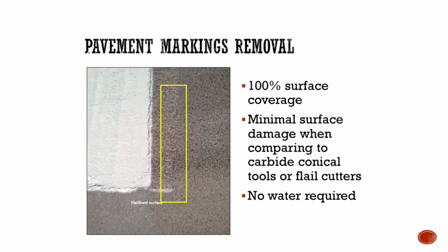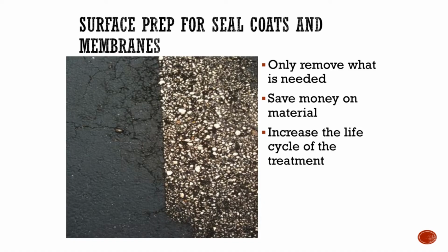Fantastic tool for pavement markings removal. In fact, we're seeing this all over the United States right now. With the flat surface, it just does a lot less damage to the surface than traditional conicals, or in this particular market, flail teeth, water blasting even. Here's a seal coat removal with the flat tooth. And only remove what's actually needed, and being able to do some sort of surface prep before these treatments.